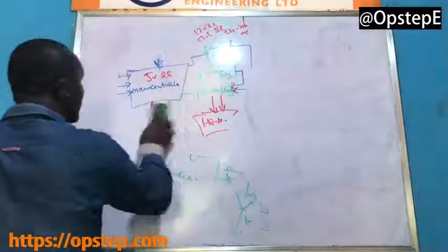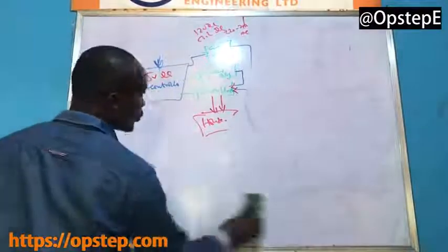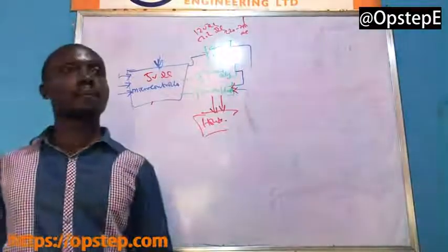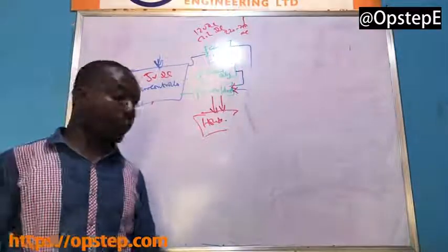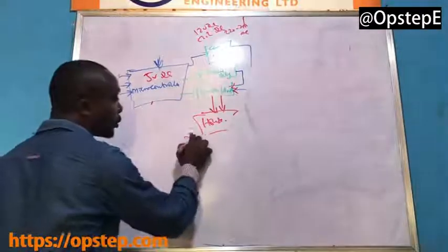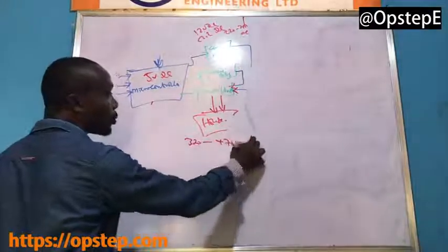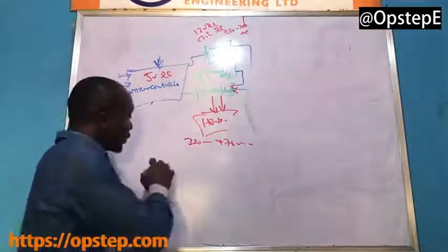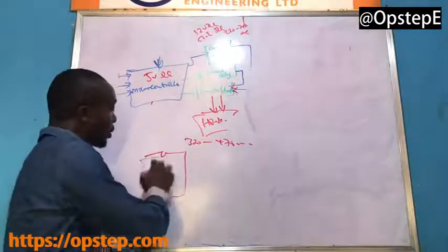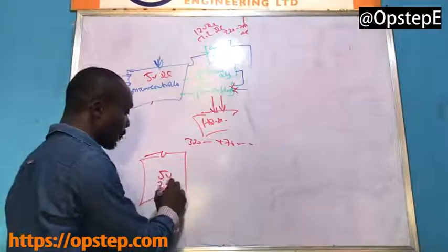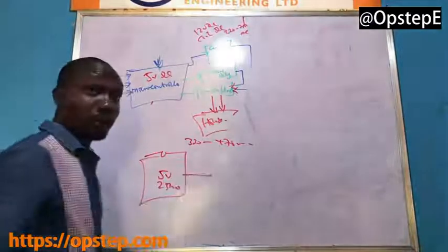So that takes this out and that takes this out. Yes. Why is it that it's a 330 ohm resistor you use for the delay? Okay, I'll tell you. Actually I could have used between 330 to 470 or even more. I'll tell you why. The microcontroller will only give you 5 volts at 25 milliamp per pin.